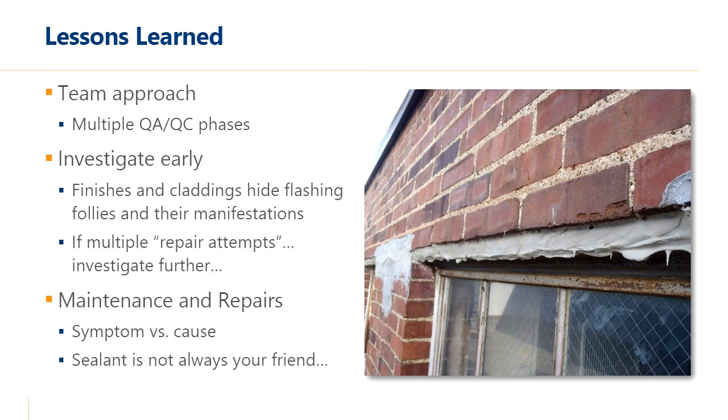I'll get on my soapbox here, but sealant is not always your friend. So in this image, you can see how in a drainage cavity system, sealing something shut that's meant to be open is really difficult. If this sealant is removed, then maybe that original weep system can perform as it was originally intended.